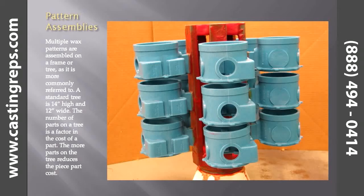Multiple wax patterns are assembled on a frame, or tree, as it is more commonly referred to. A standard tree is 14 inches high and 12 inches wide. The number of parts on a tree is a factor in the cost of a part. The more parts on the tree reduces the piece part cost.